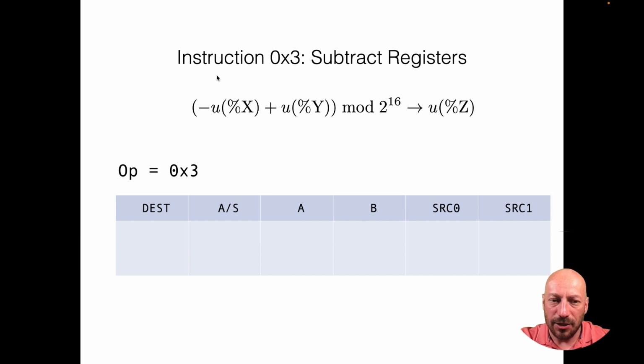So the destination register is again set, so we really could optimize away this multiplexer for this selection. And now a first time is that we are doing a subtraction, so no reason to optimize away this multiplexer. A, that's due to this AT&T thing of me, should be the bit pattern of Y, because our subtractor only can subtract B from A and not A from B. And B should be the bit pattern of X, so that means source 0 should be selecting register Y, and source 1 register X.